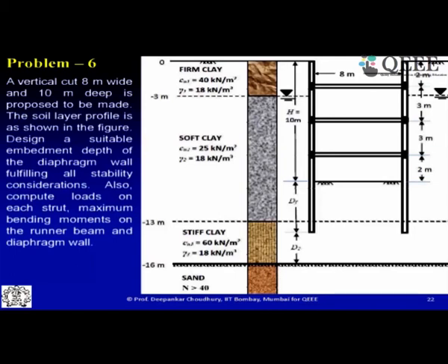clay bursting needs to be checked, and for that the disturbing force is nothing but whatever water pressure we have. How much water pressure is acting over here? You can see this is up to the sand layer we have to take, that 16 meter, and here 3 meter.